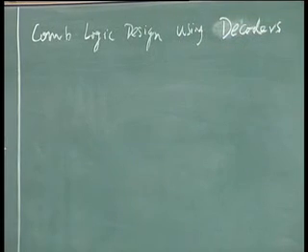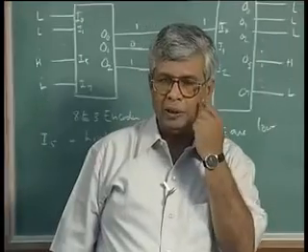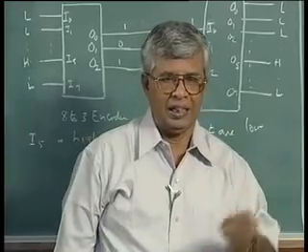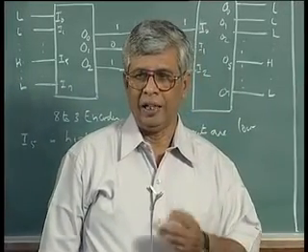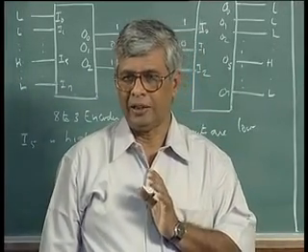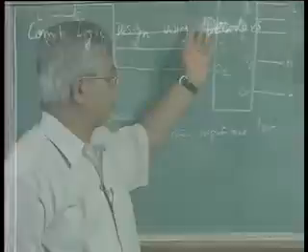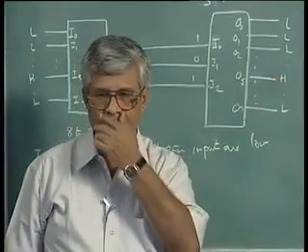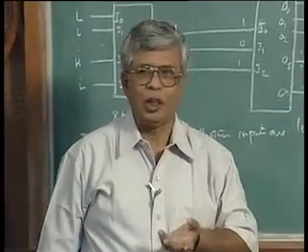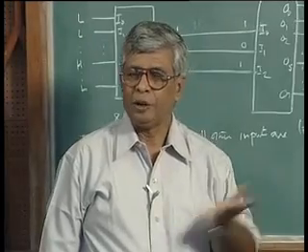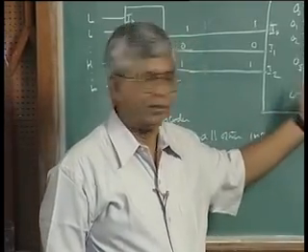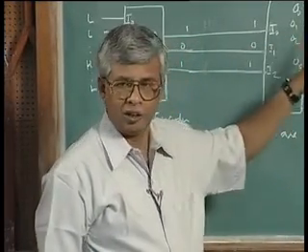With the multiplexer the mapping procedure was very clear, but here it is not even that. It is a straightforward case, because when you have 3 inputs and 8 possibilities, this is similar to the truth table, isn't it? So all possible minterms are generated. The question is, one of them will be high, all others are low.